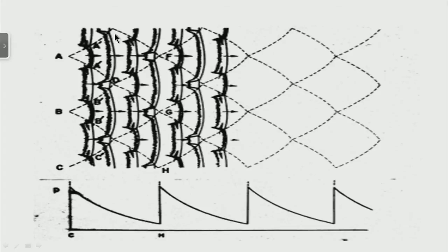It decays down, it reaches a value over here, and then it further decays, chemical reactions get coupled, it further decays, and by the time the two triple points or the transverse waves intersect, it has decayed in strength to something like 0.6 to 0.8 times the mean Mach number at which the detonation propagates.